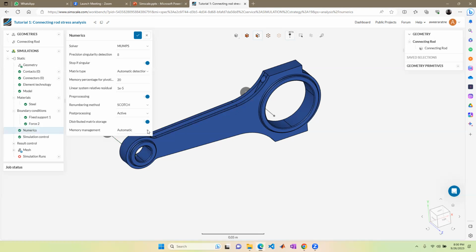It's quite intricate, and SimScale has provided us with default solver settings, and I suggest that you use it. For most of the primitive cases, this would be fine, but even when you move into a moderately complex case, you will need to look up the documentation and find which of these solver settings are most suitable.